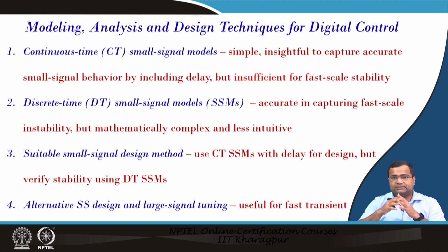Then we have also discussed the alternative small signal design method, which earlier we considered, stable pole zero cancellation, but we found this technique is very non-robust because we cannot exactly cancel pole and zero. Of course, these techniques are also not very effective for shaping output impedance because we are mainly targeting the loop shaping approach, but in closed loop output impedance we also have an open loop output impedance in the overall transfer function. As a result, these methods are not robust when the load current varies.